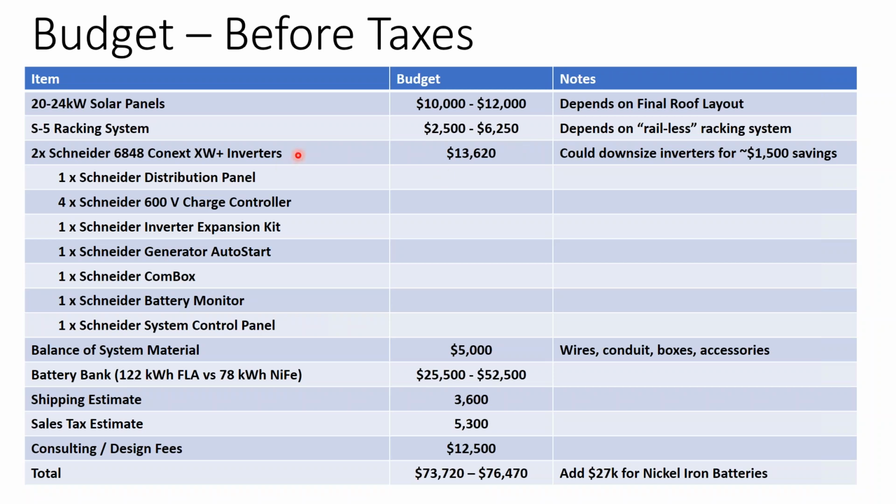And of course, mainly the fundamental cost is that batteryless inverters are one way. They go from the solar array out. Battery inverters are two-way. Either you're buying a charge controller and a two-way battery inverter, or you're buying a one-way inverter and a two-way battery inverter.